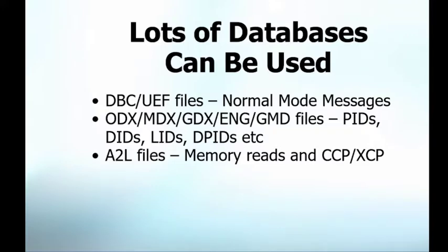The industry is slowly moving to all using ODX. And if you're not using ODX, you're probably using a version of ODX, and you just call it something different like GDX or ENG. They're all essentially XML-based formats. Those files are what contain all your diagnostic information. And then A2L files are what you use for CCP/XCP or doing direct memory reads to an ECU. So there's one screen to load all of this.